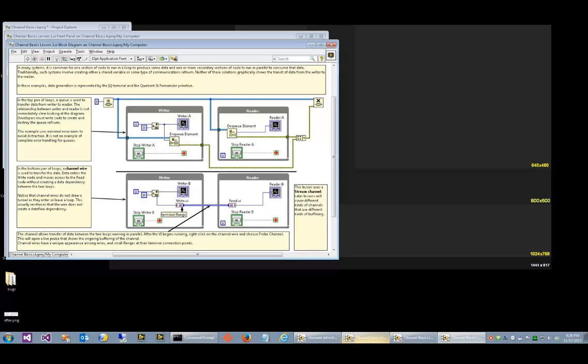These do not create a data flow dependency. So it's not like they're going through the gates of your loop as an input or an output. Instead, they're jumping over the wall and running across to the other guy because they're carrying data while the two loops are still running. I still say you should use a bridge symbol for that. We've debated various things. Of all the graphics that we've tried to put in there, nothing has appealed to people quite as much as just nothing there, because it blatantly looks like that wire isn't inside that loop.